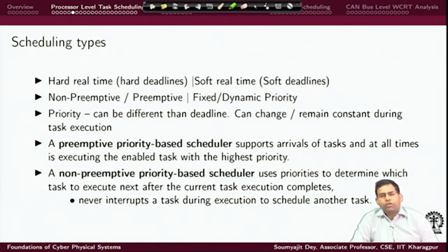If you remember, we talked about static scheduling, where task decisions were made statically offline before the system was online, and dynamic scheduling, where task decisions were made during the system's execution. In a similar manner, we can think of fixed and dynamic situations with respect to task priorities also.